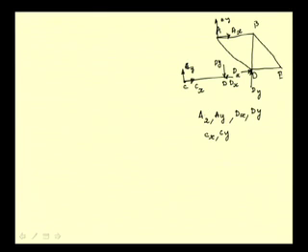So, now we see that we have 6 unknowns to be determined, and if I designate this as free body diagram 1 and this as FBD 2, then from these two diagrams we have 3 plus 3, that is 6 equations, and we have 6 unknowns to be determined. So, this problem now becomes statically determinate. Once we have determined these external reactions and the force at D, we can use the method of joints to determine all the internal forces.